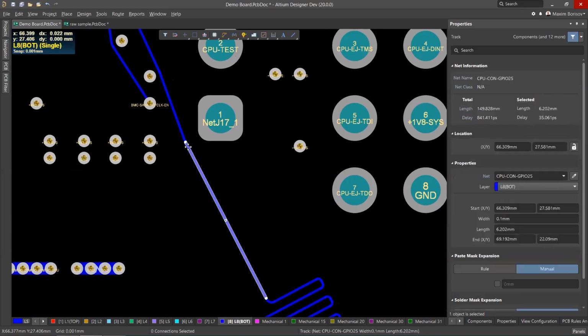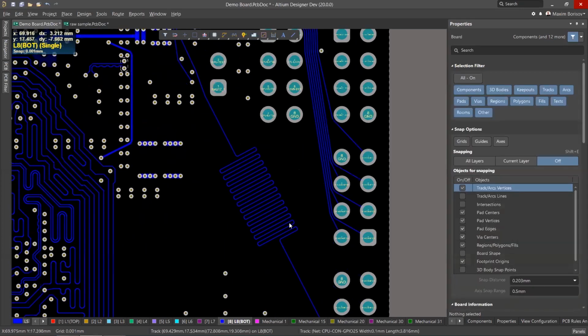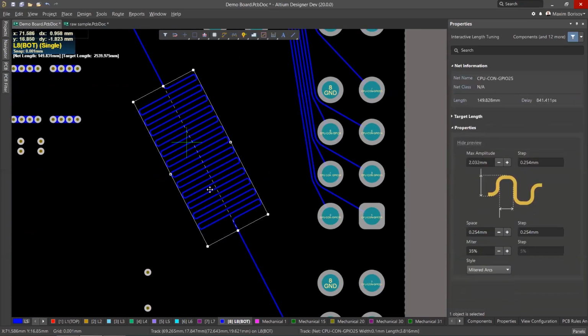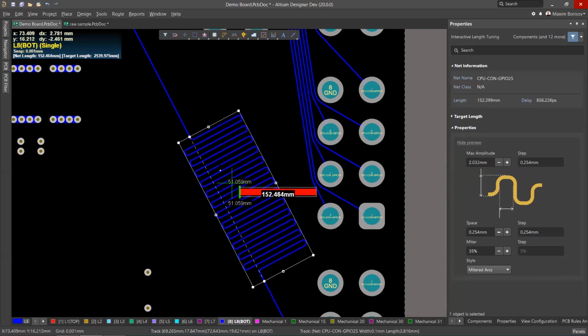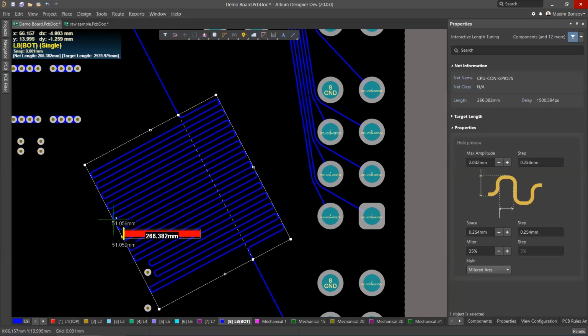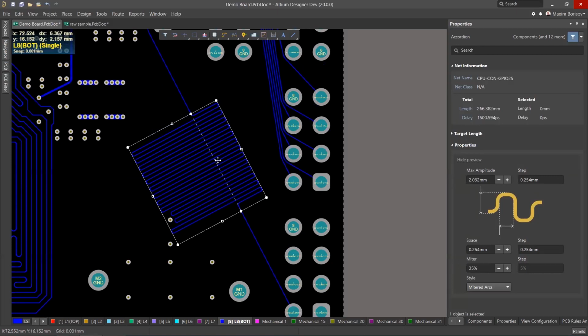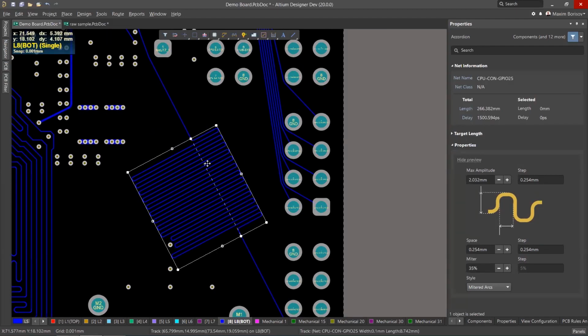Just to confirm, that's exactly that kind of trace that we managed to get in the previous stages, odd angle segments. And you can effectively slide the boundary in any direction, change the amplitude. You can see, it's recognizing its surrounding. So, an extremely serious boost for high-speed designs. And it's a fast acting mechanism. It's working fast, no matter how dense your board is.